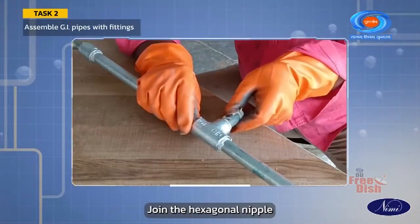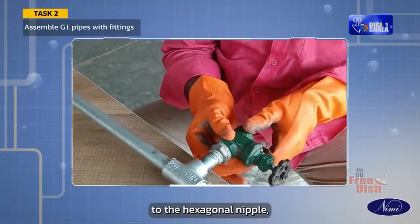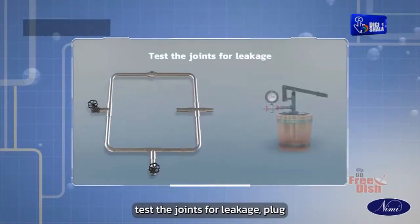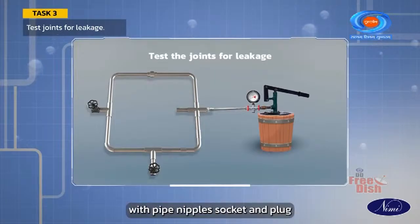Join a hexagonal nipple to the left side of the T. Assemble a globe valve to the hexagonal nipple. Test the joints for leakage. Plug all the openings in the section of test line with pipe nipples, socket and plug.